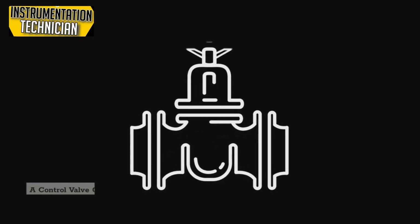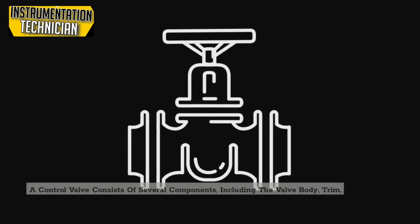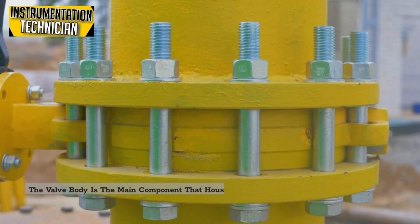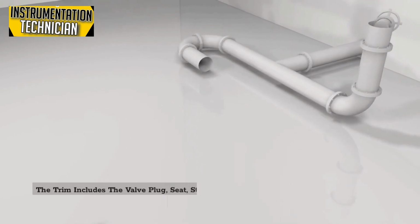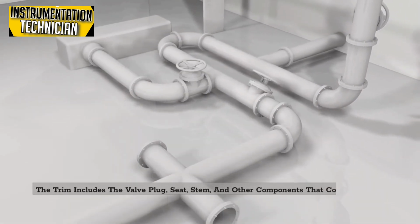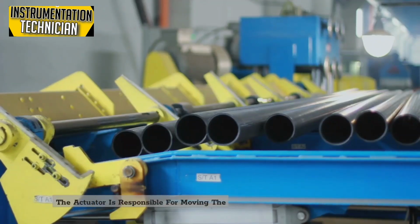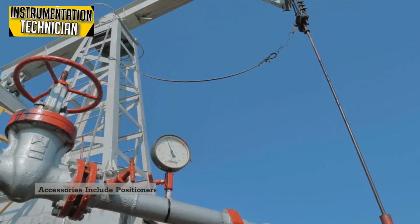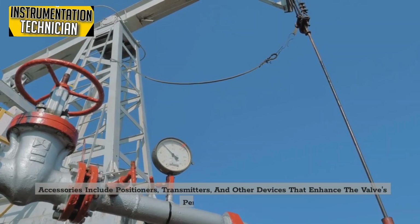A control valve consists of several components, including the valve body, trim, actuator, and accessories. The valve body is the main component that houses the trim and provides the interface with the process piping. The trim includes the valve plug, seat, stem, and other components that control the flow through the valve. The actuator is responsible for moving the valve plug to adjust the flow rate. Accessories include positioners, transmitters, and other devices that enhance the valve's performance.